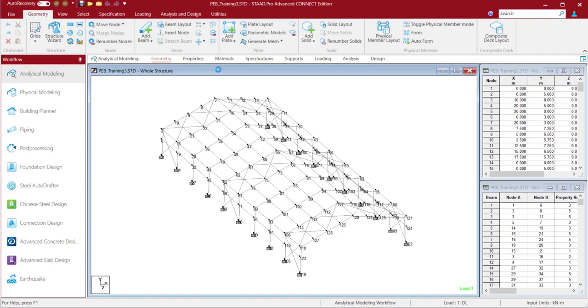But the reality is sometimes these connections are very much susceptible to fail because, first of all, most of the moment connections experience a huge amount of moment at that joint, and also most of the connections, say for example, the beam end forces, the shear forces you take, normally these forces are maximum at the connections. So your connection has to be very well designed, very stable, and strong enough to take any kind of target design requirement.